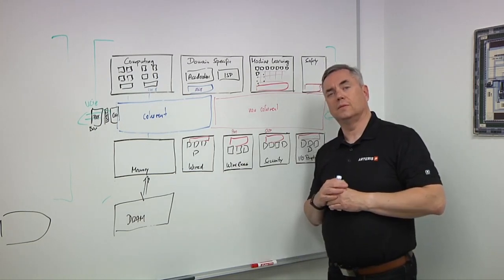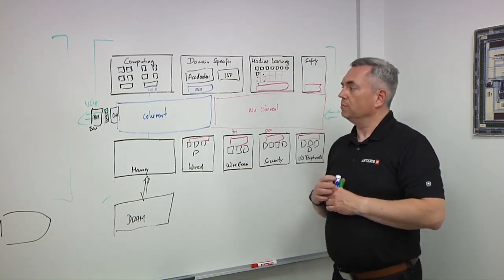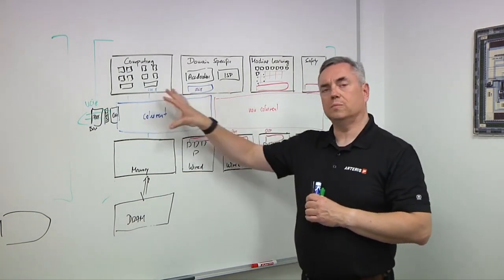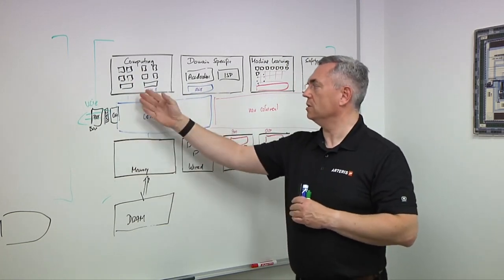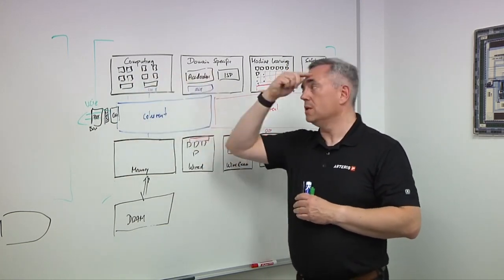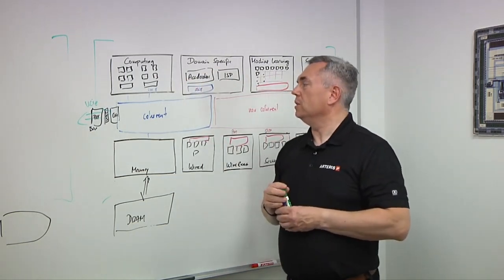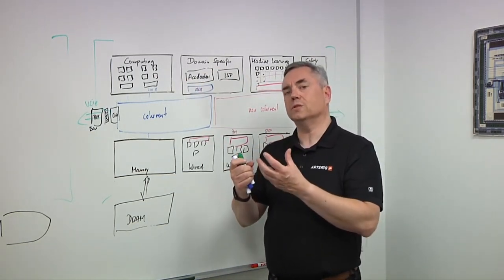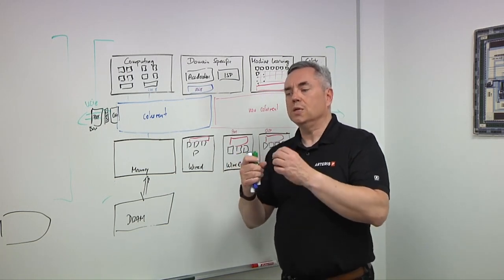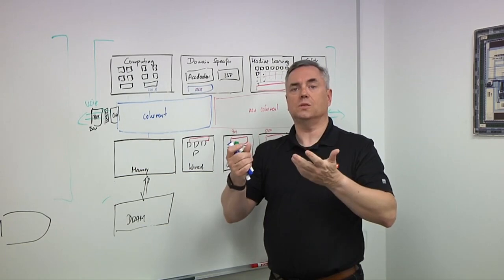So you've got all these things connected. Now, what do you really have to think about from a RISC-V perspective as you're designing these chips? So beyond the NOC, beyond the interconnect and the protocol you choose wisely, right? CHI, ACE, AXI for the non-coherent parts here. You need to really understand the ecosystem of the RISC-V core too, right? So connecting it sounds easy at first sight, but there are other things to be considered.